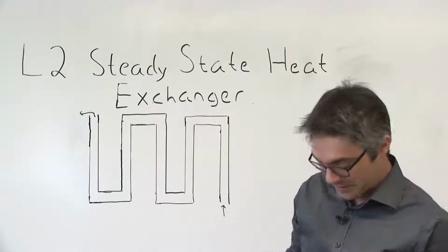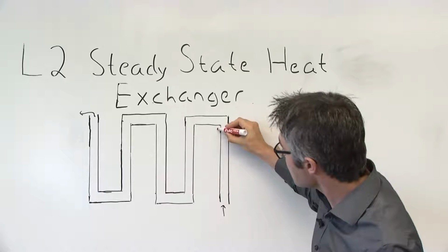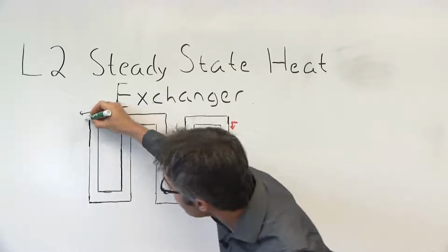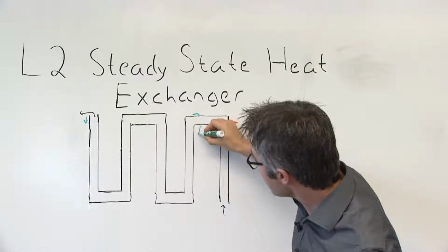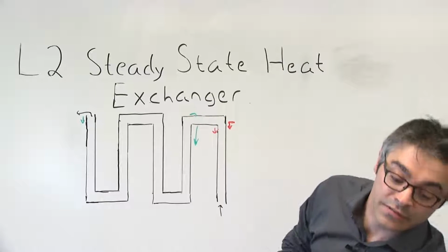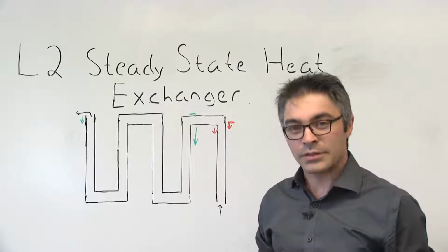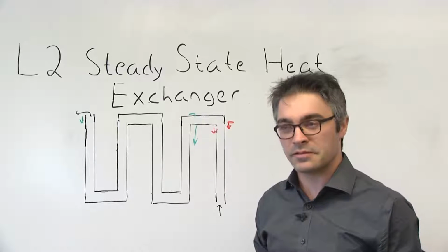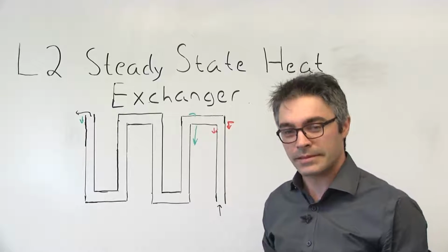During the course of this adventure, the water is going to be heated by steam in countercurrent, starting with the first pipe, and then subsequently cooled via cooling water via all 4 other pipes, finally draining out at approximately here. The goal of this laboratory will be to find the overall heat transfer coefficient for the entire system. You're going to be doing this both experimentally and theoretically through a combination of different relationships that will involve the Nusselt, Prandtl, and Reynolds numbers.